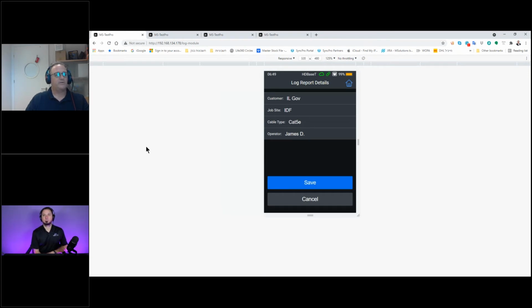So if there is a glitch on the HDMI that we recognize, we can tell you immediately, listen, there is a problem with the source. The source is showing 4K all the time, and at a certain time it's showing full HD, and we can point it out to you. Or HPD problems we've seen from displays that are getting into a standby mode, where the HPD is toggling. There are many real-life things that we can detect that are very difficult to understand and to capture.